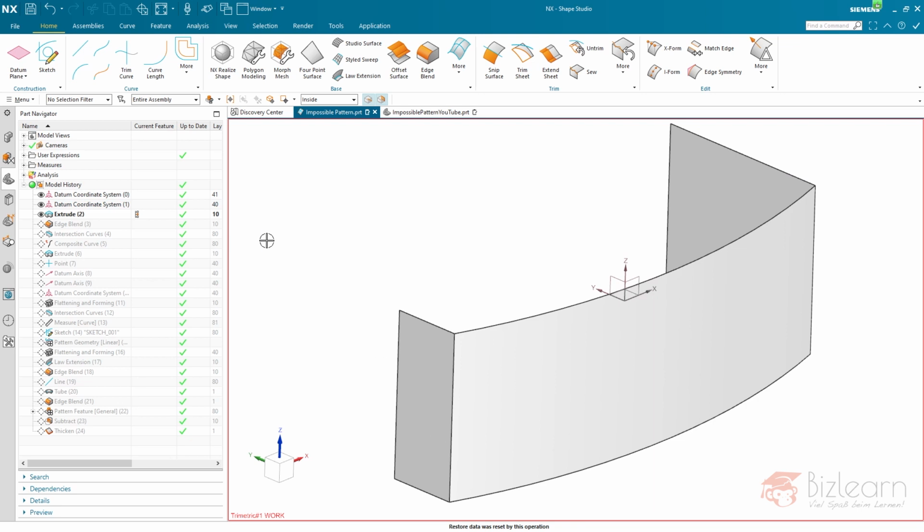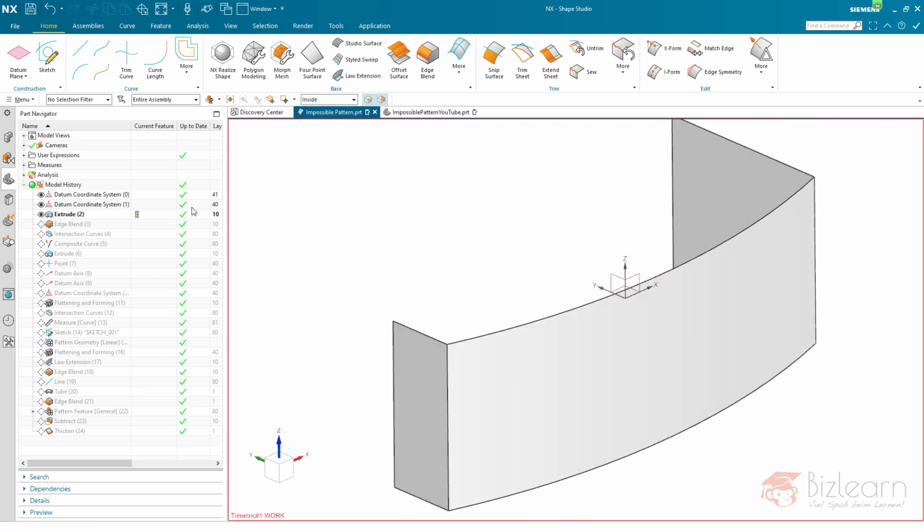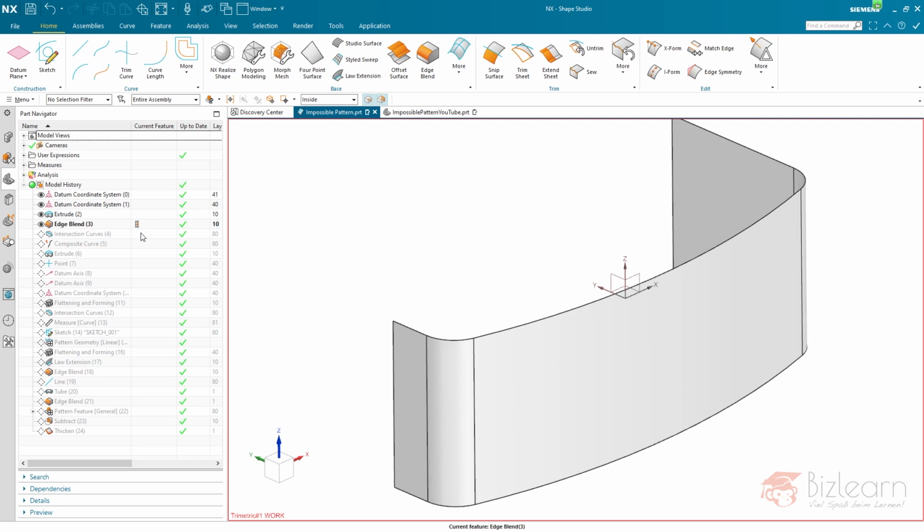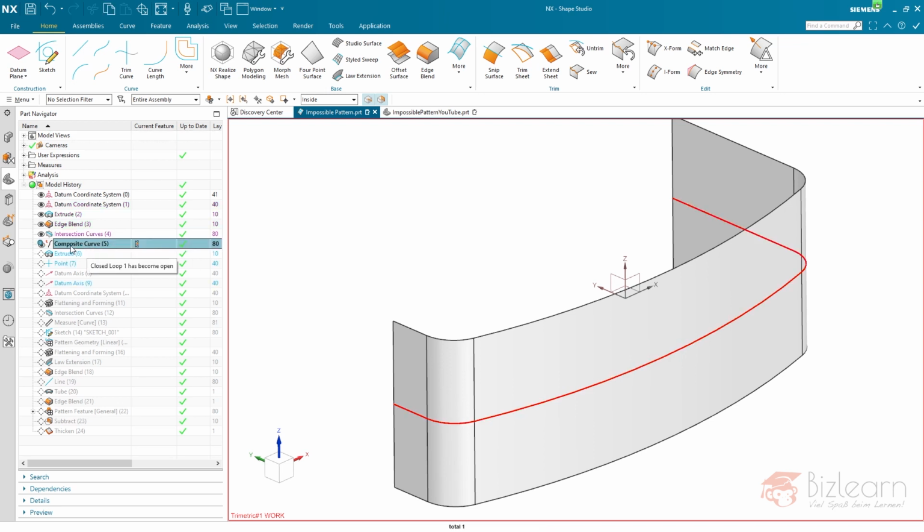I'm going to proceed with the creation of my guiding, meaning an extrude, which I am going to blend. As you can see, an intersection curve, which is joined, is going to be used in order to create a composite curve. As I mentioned before, that is the join of the curve. So the result is one single curve, which is extruded again. Compared to this one, there are no internal face edges, which is important for the next steps.